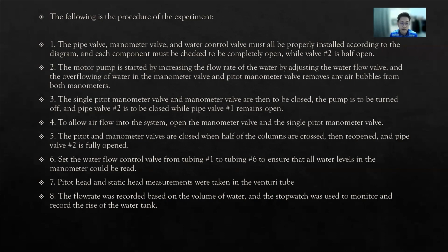Pitot head and static head measurement were taken in the venturi tube. The flow rate was recorded based on the volume of water, and the stopwatch was used to monitor and record the rise of the water tank. That's the last step. That's all from me.